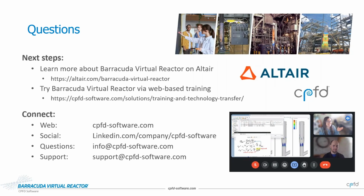And you guys talked a lot about particles. How many particles can Barracuda Virtual Reactor handle? Yeah, there's really no limit to that. Every time I get asked this question, it's a different answer over the years. So Barracuda Virtual Reactor takes the physical particles in the system, which in some of those FCC regenerators, where your average particle size is under 100 microns and they're 10 meter plus diameter, you have, we did some math, 10 to the 16 plus particles in that system.